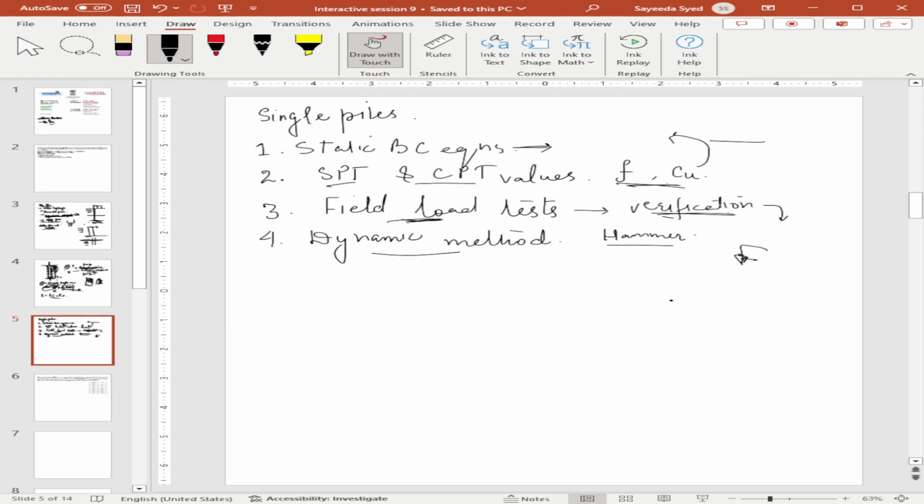So, in order to develop desired load capacity, point bearing piles must penetrate into the dense soil layer sufficiently. But it cannot always be satisfied that the penetration depth is exactly reached, because soil profiles may vary. I have dug a borehole here, but then the soil profile may be a little different here. So dynamic equations are used to determine whether the pile has reached satisfactory bearing value at predetermined length or not. It is a verification test.